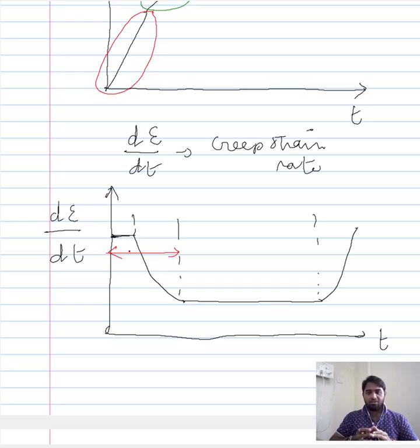And here we have plotted the slope that has helped us to categorize the creep curve, and there is also a similar reflection in the slope of the curve over the period of time. So how the slope varied is rather natural, because based on the slope only we were able to categorize or section the overall creep curve. And when you give a graphical representation to the slope, that is the creep strain rate over the period of time, the stages are completely visible in this plot as well.